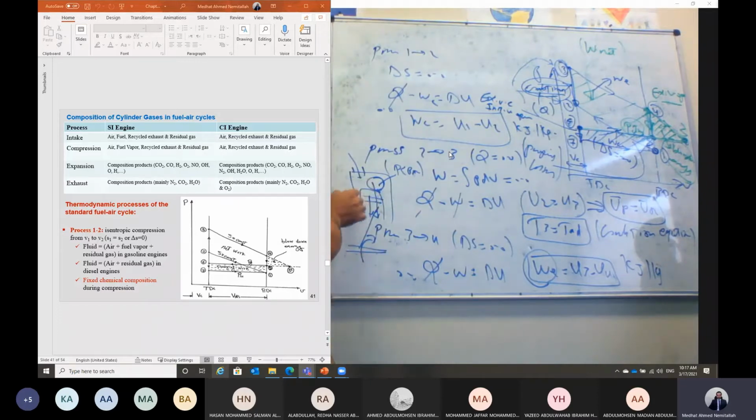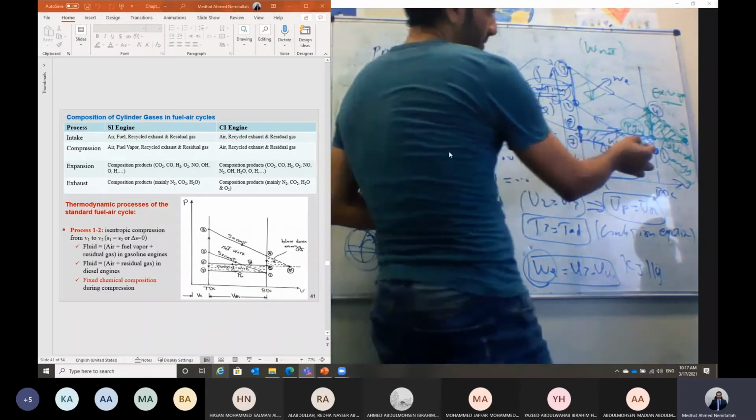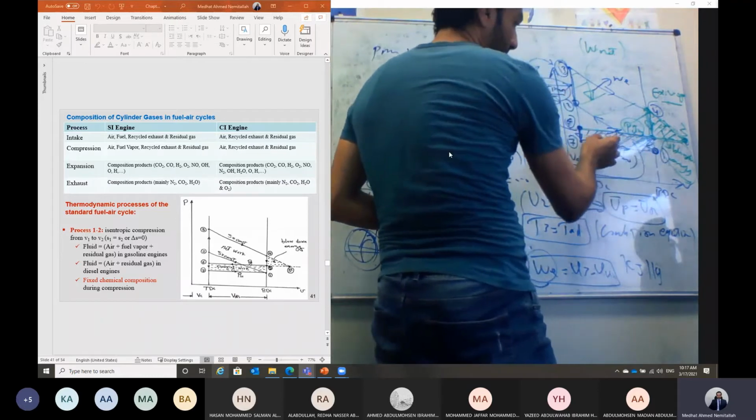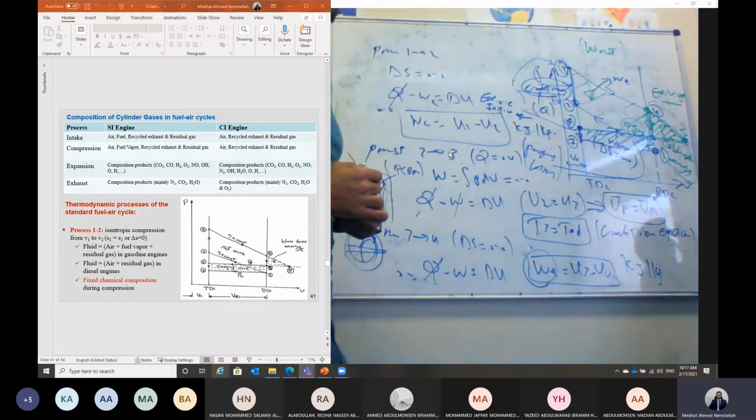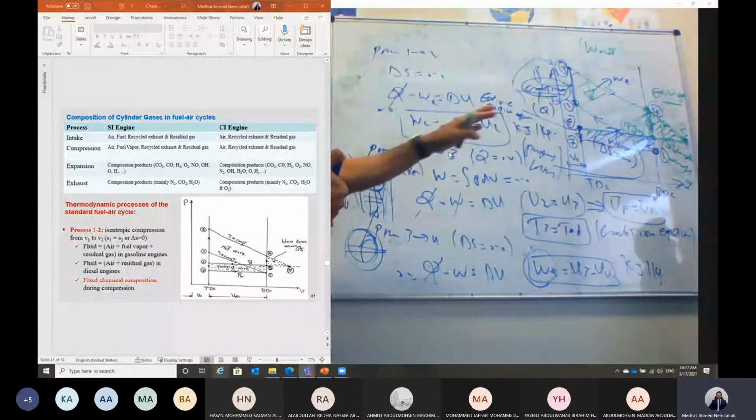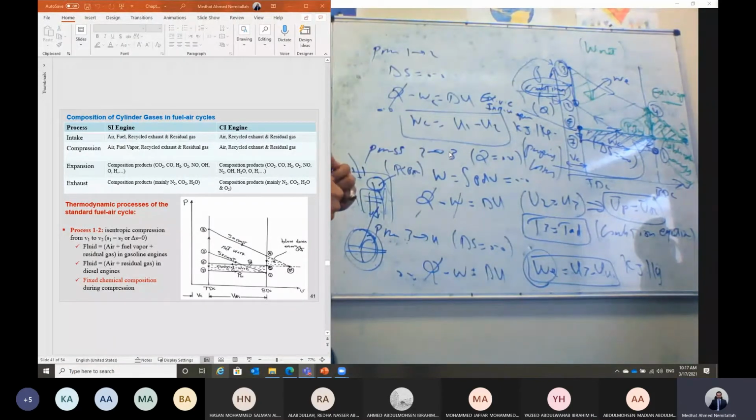This piston here is connected to the crankshaft. So during the intake stroke, while the piston is coming down, it is consuming part of the power of the crankshaft. And also during the exhaust stroke, the piston takes power from the crankshaft. This power during the intake and the exhaust stroke can be represented by this rectangular area, and we call it the pumping losses. But in this case, this is a naturally aspirated engine.